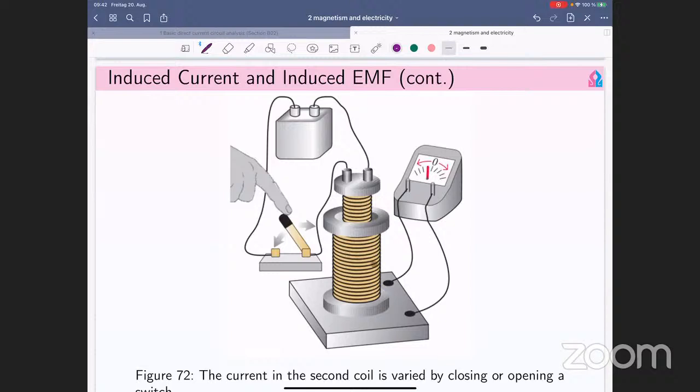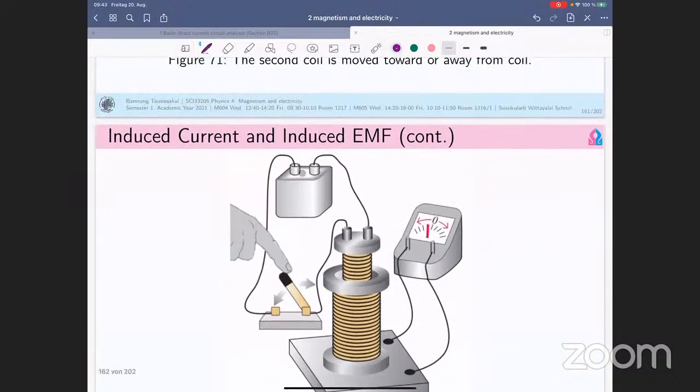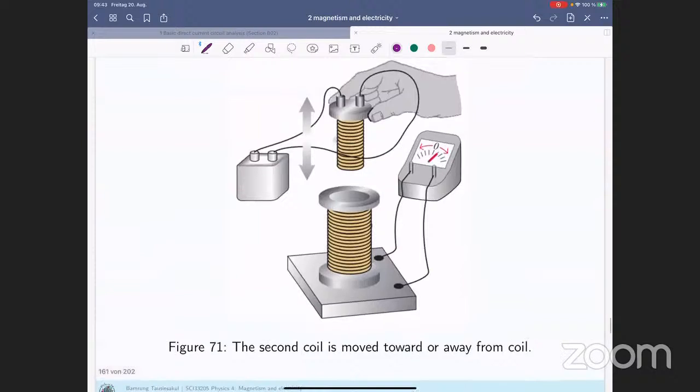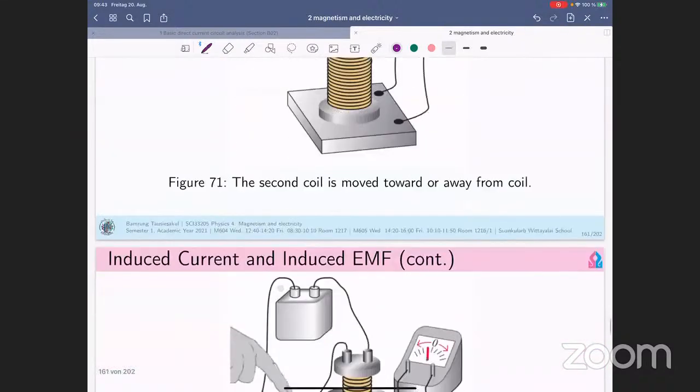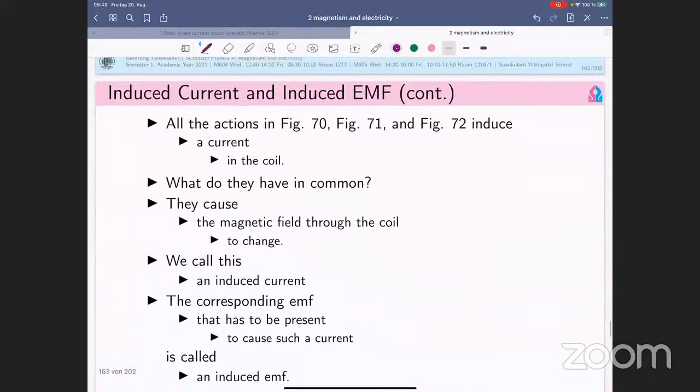This coil is not happy. It will generate a magnetic field against that, and in order to do so, it should produce current by itself, and the current will appear in this ammeter. You can observe the current by using the ammeter. That's the switching way. The earlier one is the mechanical way to change the magnetic field to this conductor. That's the whole thing that happens.